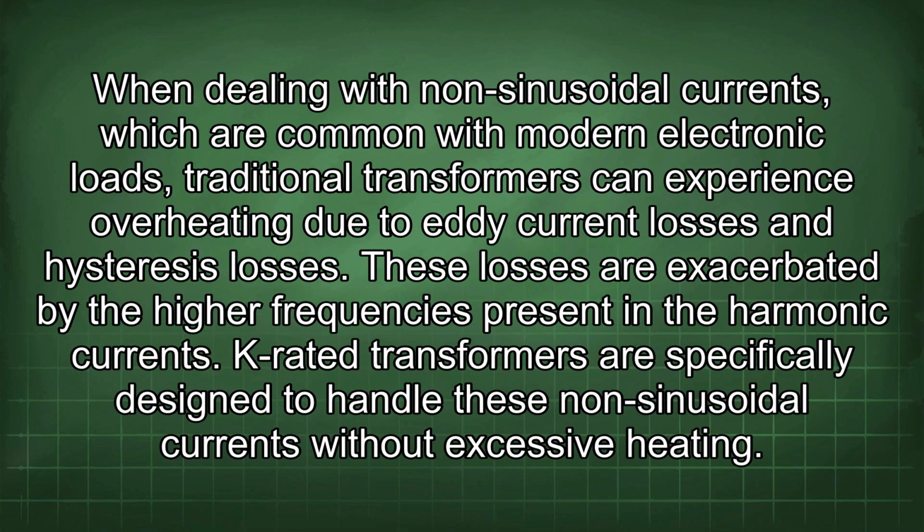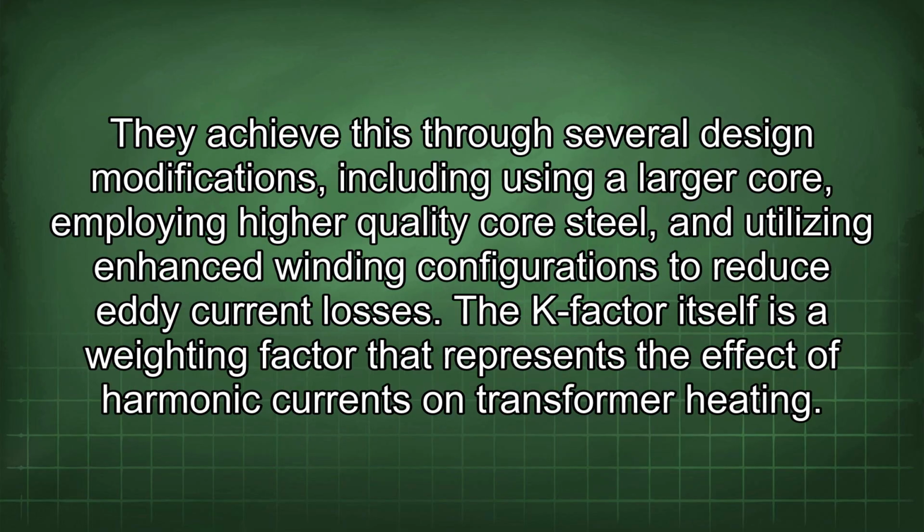When dealing with non-sinusoidal currents, which are common with modern electronic loads, traditional transformers can experience overheating due to eddy current losses and hysteresis losses. These losses are exacerbated by the higher frequencies present in the harmonic currents. K-rated transformers are specifically designed to handle these non-sinusoidal currents without excessive heating. They achieve this through several design modifications, including using a larger core, employing higher quality core steel, and utilizing enhanced winding configurations to reduce eddy current losses.